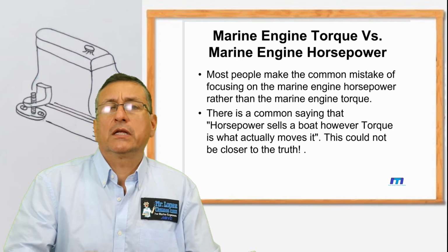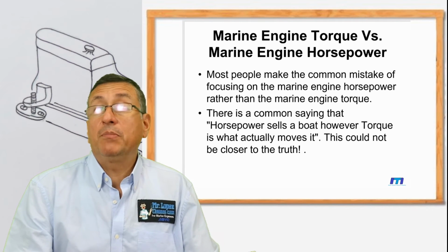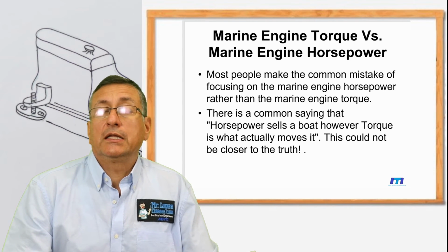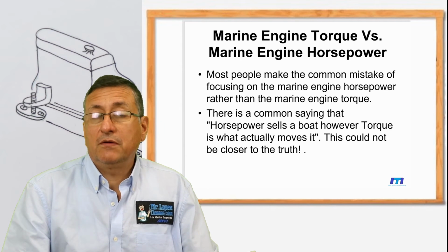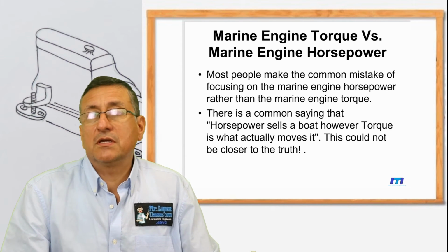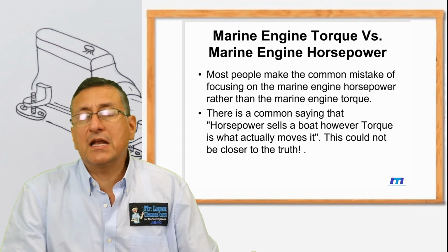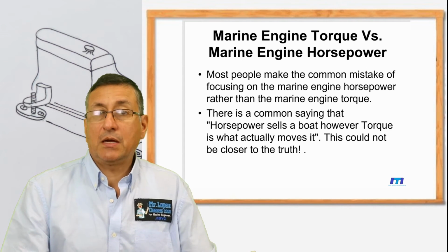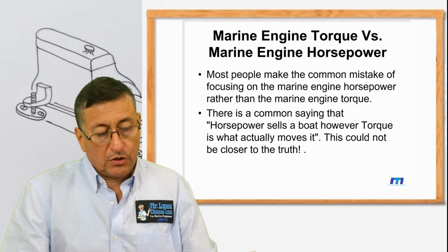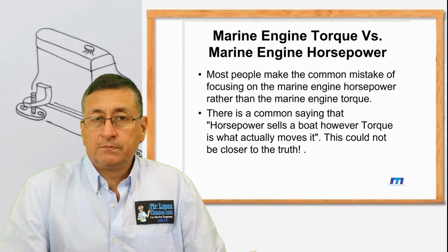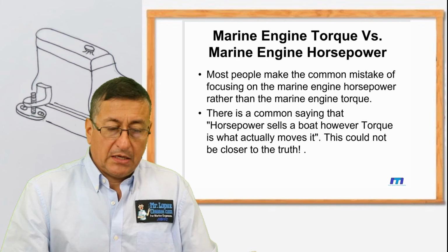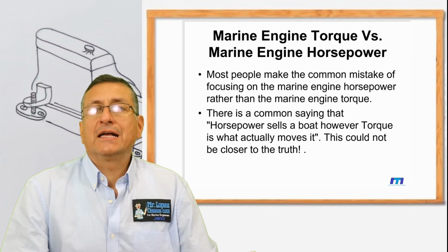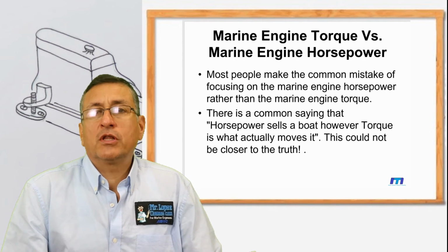other different factors like the weight, the length of the boat, the pitch of the propeller, the type of propulsion system, if it's a stern drive system, if it's inboard, if it's V-drive. Depending on the propulsion system, the weight, the horsepower, and the type of hull, we are going to calculate the thrust. But the element that is important for us is the torque, more than the horsepower.